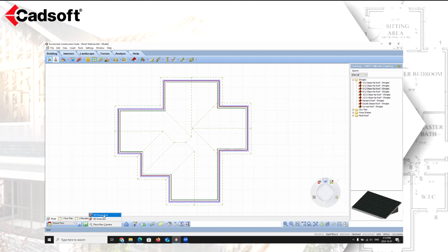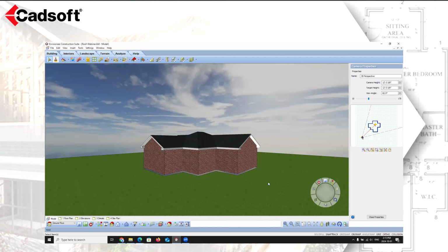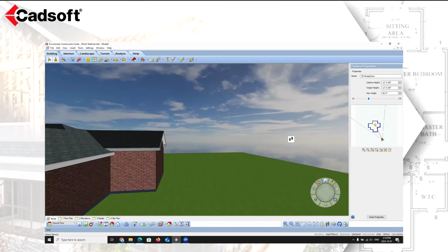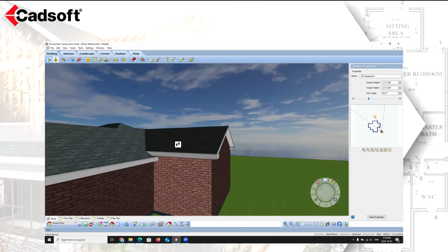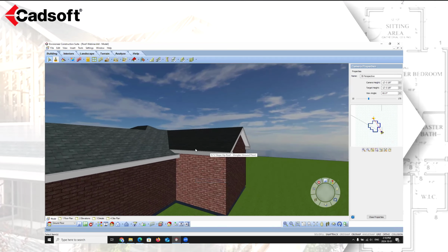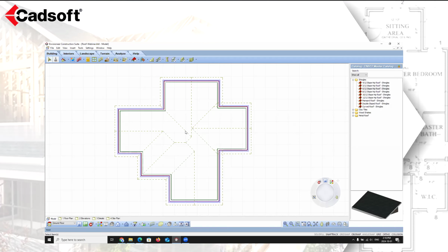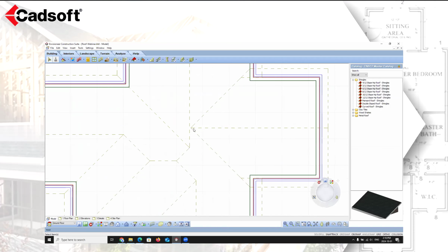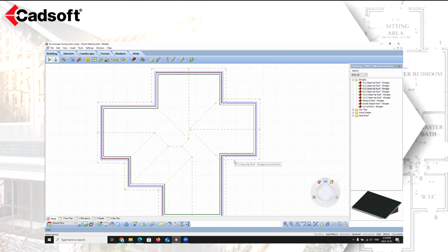There we go. And so now when we go into our 3D view, and if I pull this camera around, we can see the walls and the roof are a bit higher on that edge. Now, the issue was I raised it up over top here, so it was removing this surface of the roof. So I just want to make sure that I'm not going past the main roof, and that should alleviate the problem that we were seeing there.